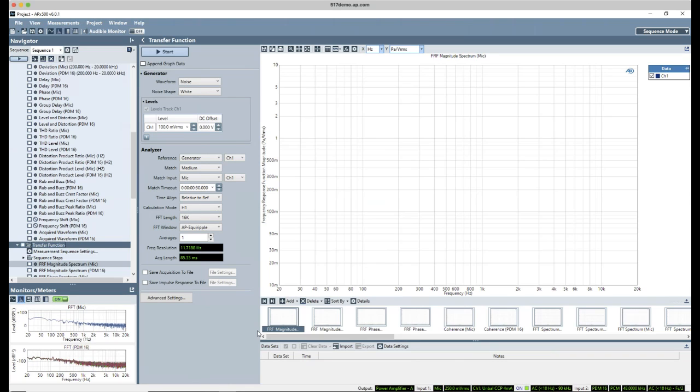So a common application of microphones is, of course, in voice applications. And in any kind of voice application, let's say a smart speaker or mobile handset, there's a good chance that there's an active signal processing algorithm that's eliminating non-voice signals. It's eliminating things like sine waves. So the advantage of transfer function is we can really use any test signal. The only thing we have to be sensitive to is the test signal has to have energy in the region of interest. So let's go ahead and make this measurement.